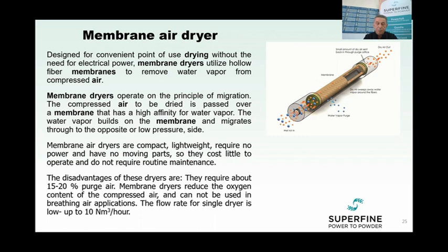Some general recommendations for dryer choice. Don't always specify a dryer. Operating every part of a compressed air system at the lowest possible dew point is rarely necessary. It's expensive and almost always wasteful.